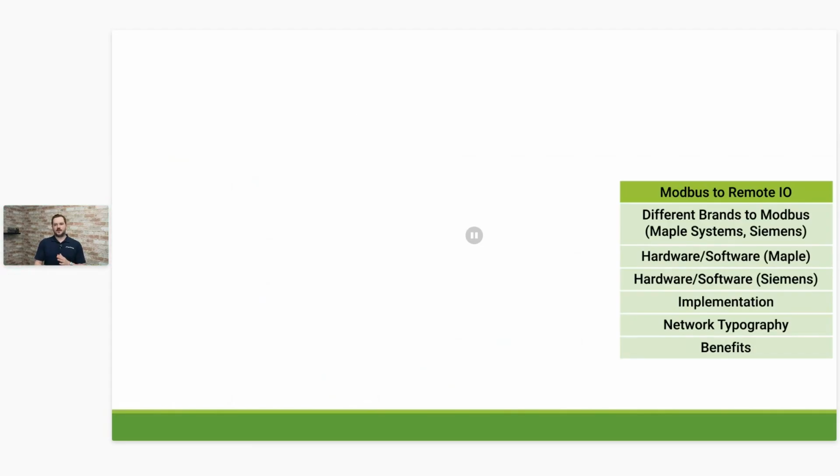Kind of a tough question to answer because there's not an exact length. You'll hear 100 feet a lot of the times for that before you start to see it. Really, it's going to be dependent on the brand of the sensor that you're using, the type, obviously, something like a thermocouple versus a pressure sensor or a water level sensor, are all going to be a little different. Biggest thing to look out for is if you start to see some serious loss in signal quality, that's probably when it's about time to implement remote I/O. Ideally, you want to keep that analog sensor just as close to whatever you're measuring as possible.